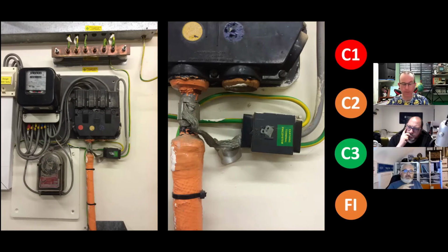Aha, doesn't that look like that? An earth terminal may not be appropriate on a PME network. In such cases, consideration should be given as to whether to proceed with conversion and make alterations as are necessary to the installation of such affected customers, or to make the changes to the network in a manner which preserves the essential separate neutral and earth characteristics of the network and the supply connection.